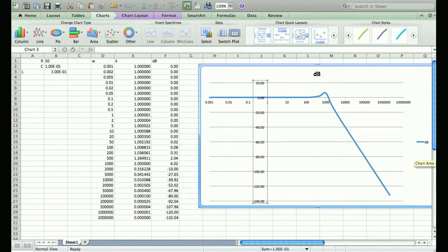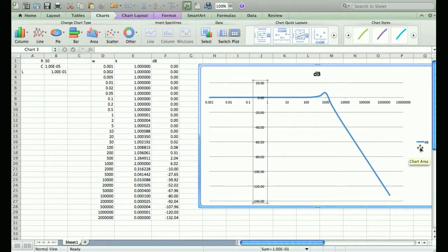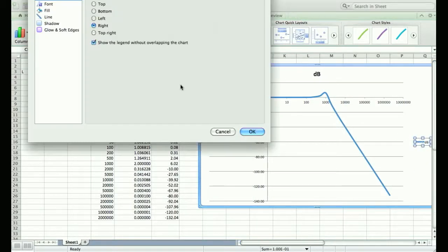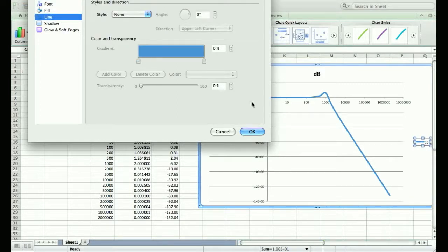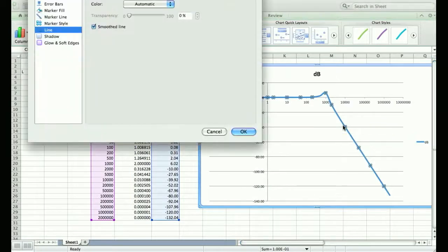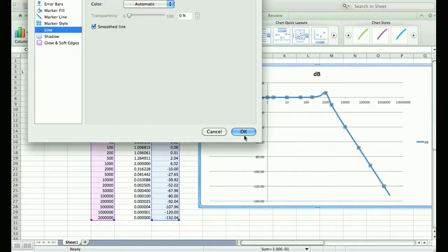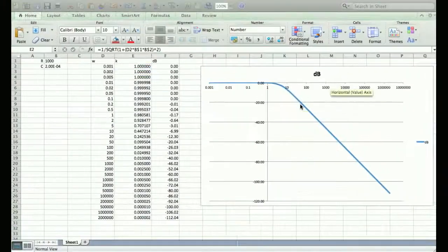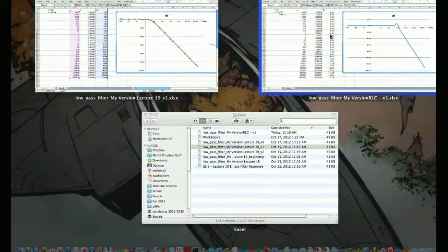Can you repeat this? Yes, I can. What part? 20 dB. Yes. Okay. So the RC circuit, which is represented by this faint red line here, falls off. In other words, the slope of the linear part of it is about negative 20 decibels per decade. But a two-pole filter will fall off at twice that, at 40 decibels per decade.